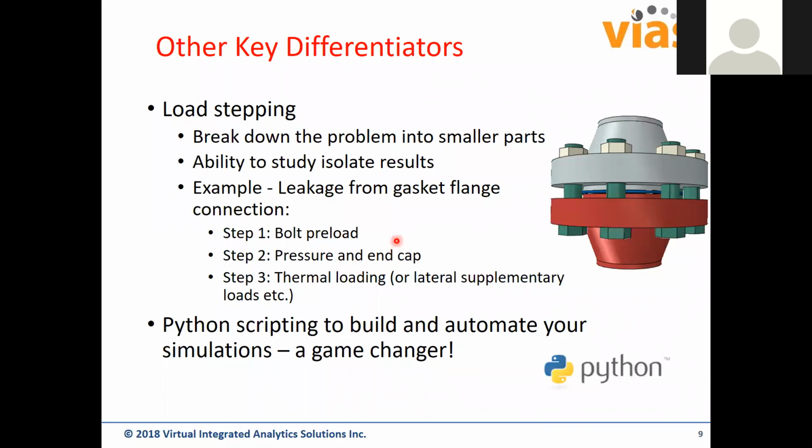One thing which I find very interesting with Abaqus, and most of us these days have some understanding of Python, the scripting language, is that whatever Abaqus model you create is completely convertible into a Python script, and then you can tinker around, change things that you want within the script itself, and even automate it.